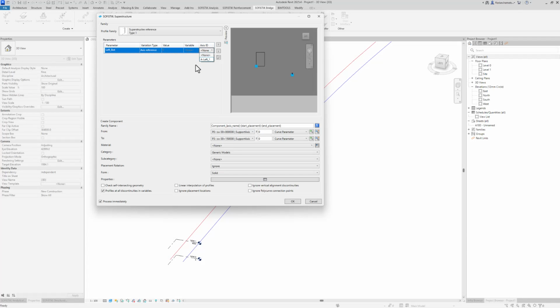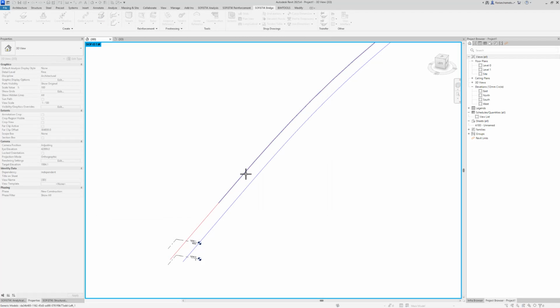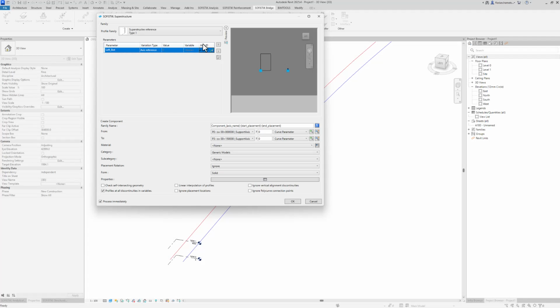You can either use the drop down to select the A underline left 1 axis, or select this green button over here to select either a curve element or an axis element. So keep in mind to use the Tab key to select the secondary axis properly and press Enter. You can also see that A1 left is selected.